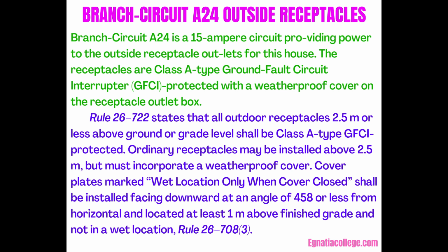26-722 states that all outdoor receptacles 2.5 meters or less above ground or grade level shall be Class A Type GFCI protected. Ordinary receptacles may be installed above 2.5 meters, but must incorporate a weatherproof cover. Cover plates marked wet location only when cover closed shall be installed facing downward at an angle of 45 degrees or less from horizontal, and located at least 1 meter above finished grade and not in a wet location. Rule